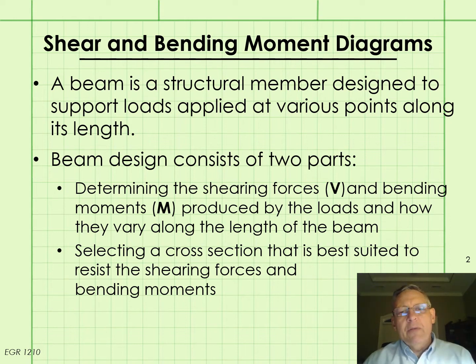A beam is a common type of structural member used in engineering that is designed to support loads applied at various points along its length. Beam design consists of two parts, the first being determining the shearing forces and bending moments produced by the loads and how they vary along the length of the beam. And the second part of beam design is to select a beam cross-section that is best suited to resist the shearing forces and bending moments that have been determined to be present in the beam.